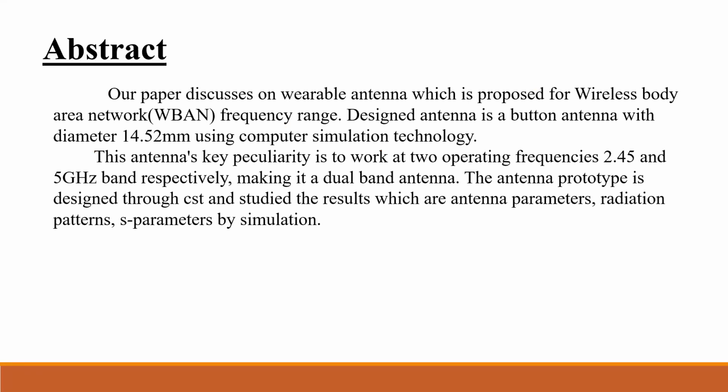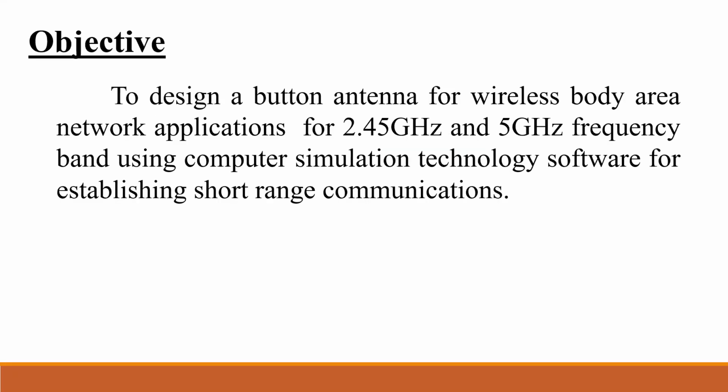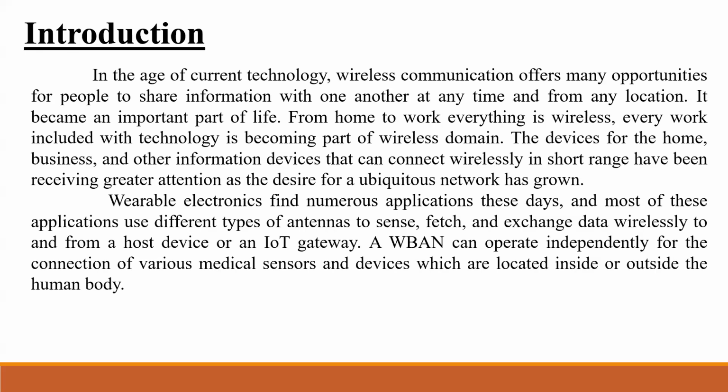Our paper discusses a wearable antenna proposed for the wireless body area network frequency range. This antenna is designed as a button antenna with a diameter of 14.52 mm using computer simulation technology. The main aim is to operate at dual band, that is, multiple frequencies called dual frequencies. The main objective is to design a button antenna for wireless body area network applications for the 2.45 GHz and 5 GHz frequency bands using computer simulation technology for establishing short-range communications.